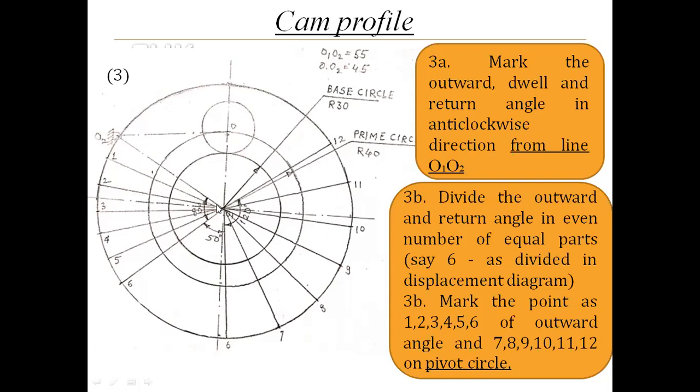Clearly understand that point. You have to measure outward angle, dwell angle, and return angle with respect to line O1, O2.